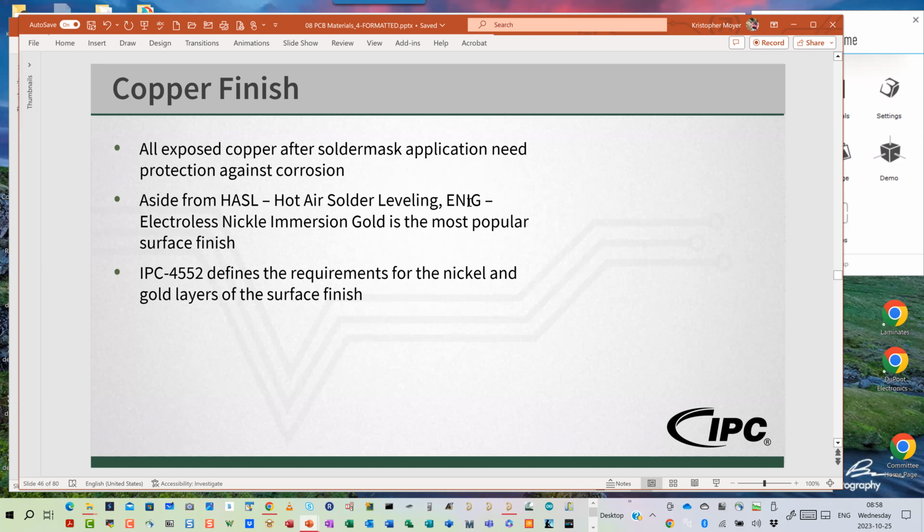So again, if you're going from fabrication and going right across the street to assembly and immediately assembling them, it's a fine process. Then the last process, ENEPIG. The military guys are actually starting to look to ENEPIG. It's now an even more costly process than ENIG, in that it is ENEPIG, right? Electroless nickel, immersion palladium, immersion gold. So it adds the nickel phosphorus layer.